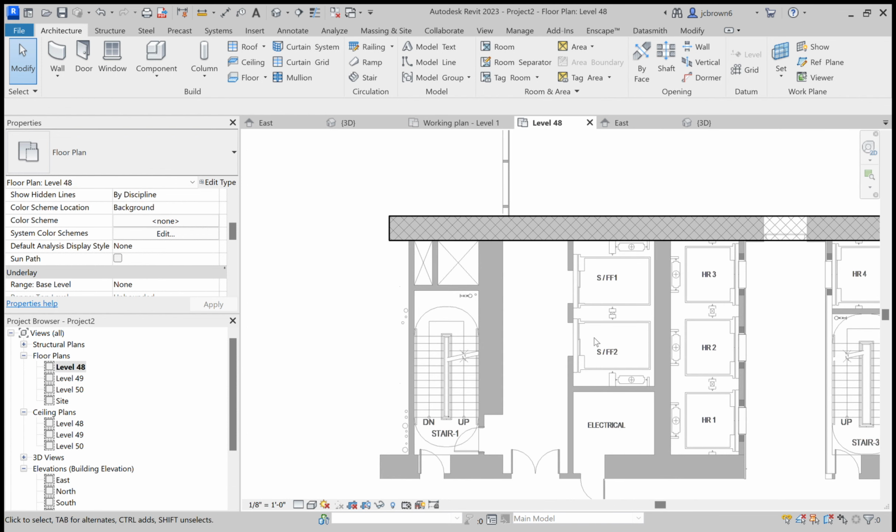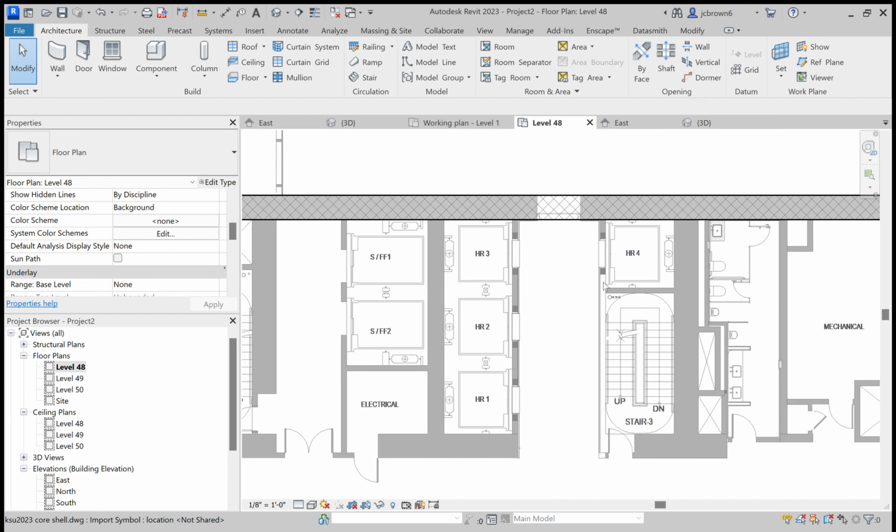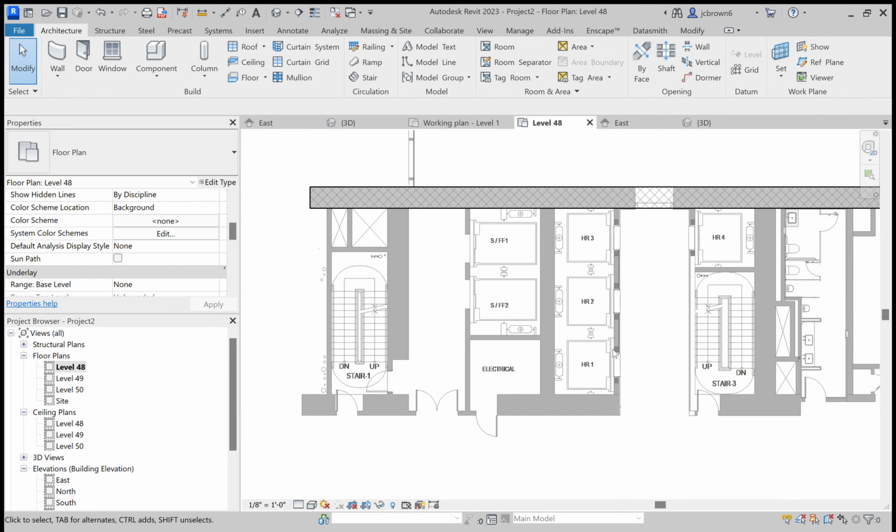But you don't need it, especially in the stairwells or in this elevator core. You will need it for your elevator lobby though. So like this 8-inch wall that you create, you'll need to create an 8-inch drywall, one that has a drywall on one side.